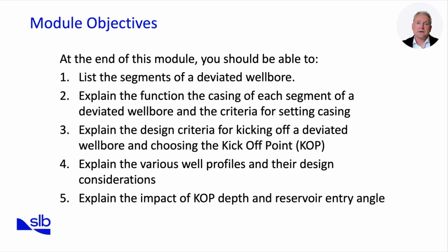You will also learn how to choose an appropriate kickoff point, KOP, in both directional and horizontal wells, considering formation strength, trajectory requirements, and re-entry constraints. The session also explains the design of curve and lateral sections, focusing on inclination ranges that promote effective hole cleaning and minimize torque and drag.